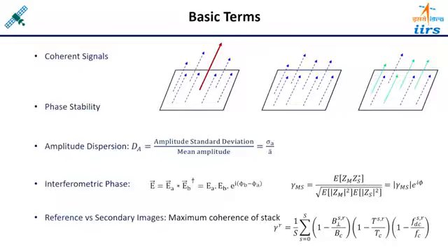So if more temporal gap is there between the images, it means they are not correlated, or you can say coherence becomes very less, or the signals are completely decorrelated. As the time difference between both the images increases, the coherence level decreases, and if this time is beyond a particular value, then these signals are completely decorrelated.